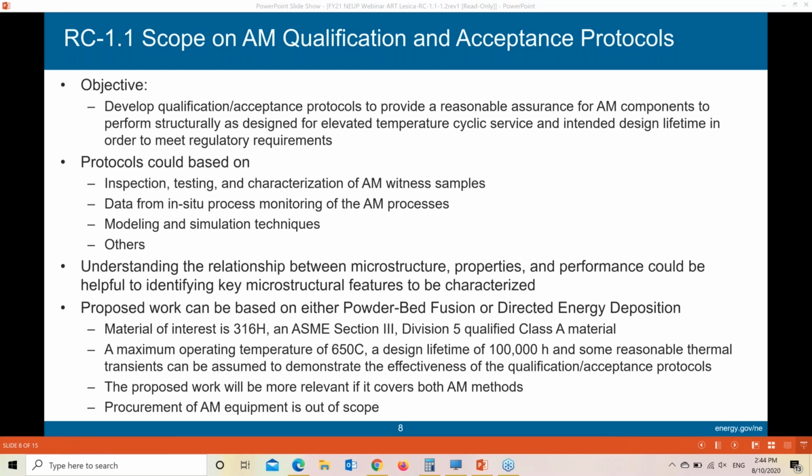For high temperature reactor applications, for stainless steel 304H and 316H, we additionally require a fatigue test, done at 600 degrees Celsius with a 1 hour hold time, and we require that the material can withstand 200 cycles